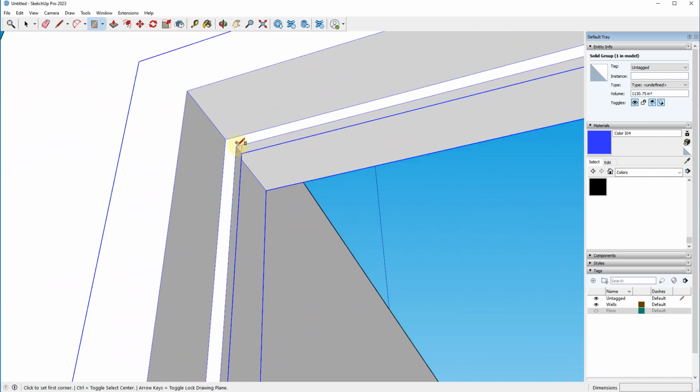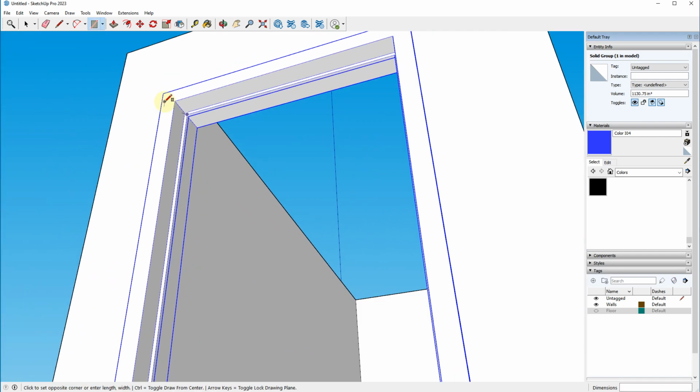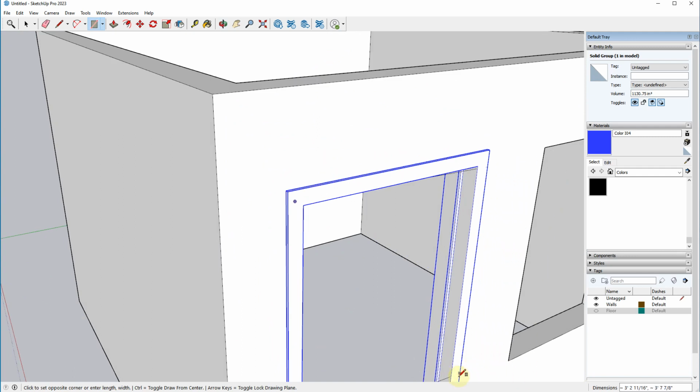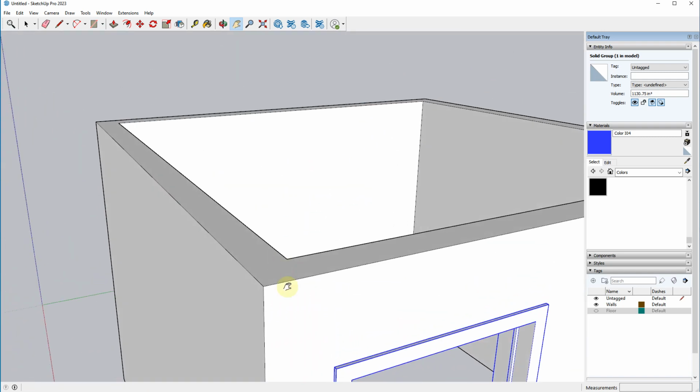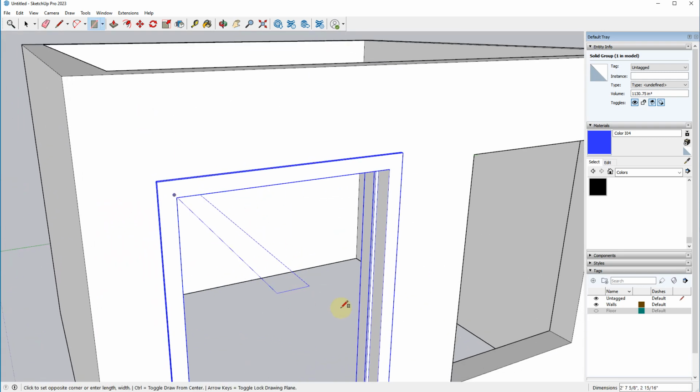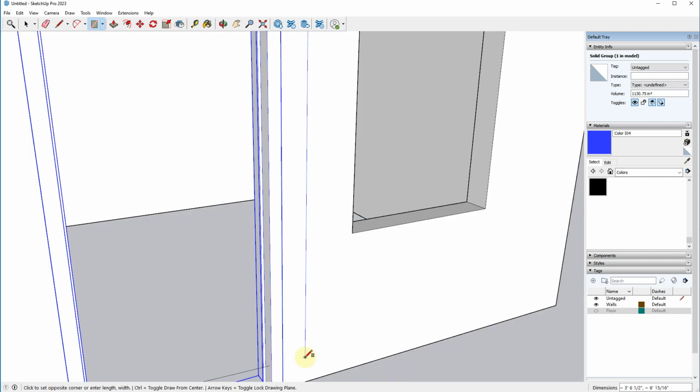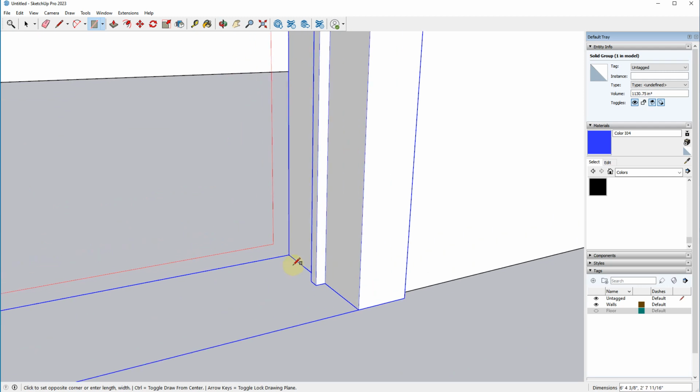So what I'm going to do is draw a rectangle, and I'm going to go from this corner right here. And this is something else that I haven't mentioned: you guys know about pan. You can hit H and then hit R to go back to the rectangle tool. Alternatively, let's say I'm still in the rectangle tool, if you double click on the middle mouse button, it'll jump you to where your mouse is. So that's a quick way to jump over to something without doing anything that might disturb everything else going on.